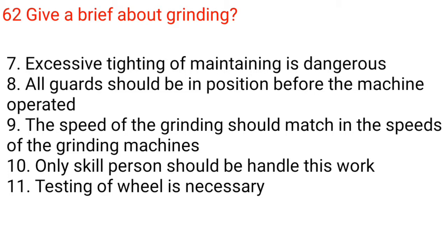7. Excessive tightening of mounting is dangerous. 8. All guards should be in position before the machine is operated. 9. The speed of the grinding wheel should match the speed of the grinding machine. 10. Only skilled person should handle this work. 11. Testing of wheel is necessary.